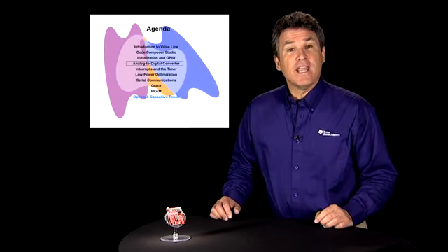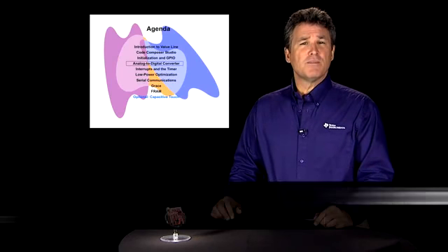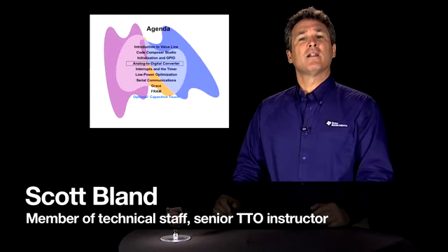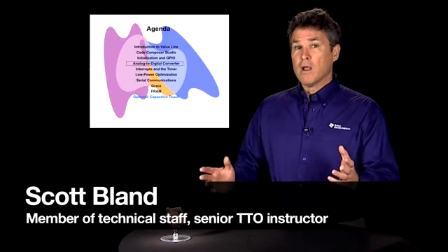Section 4 covers the analog to digital converter, or ADC. Since most MSP430 projects measure and/or control things in the real analog world, the device needs to be able to monitor what's happening out there. One channel of the 10-bit ADC is connected to an internal temperature sensor. You'll use that sensor to monitor the temperature of the MSP430 and experiment with the ADC.